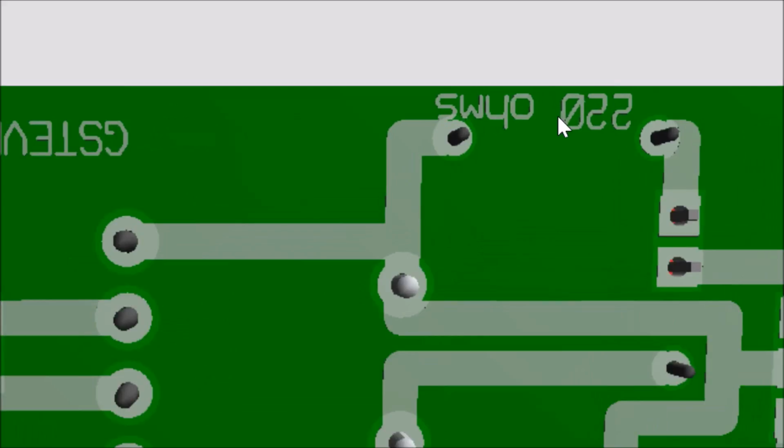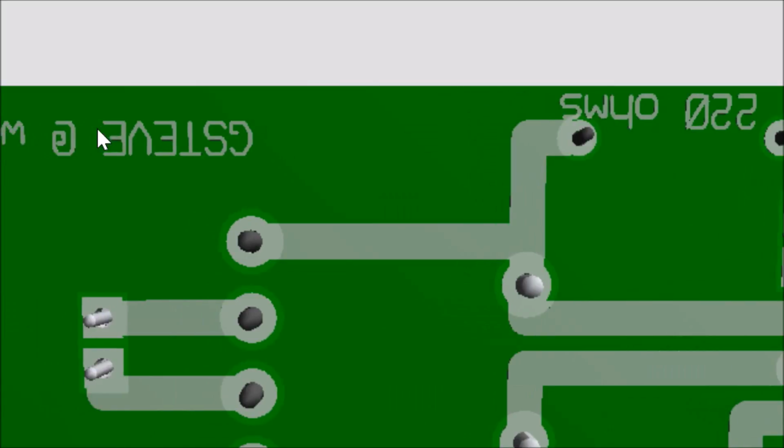I want to point out something. You can see that my LED is really touching this copper, but make sure that this and this are not ever touching together. So you can go ahead and shift this in your own design so that it doesn't touch this copper at all. Check it out and be able to separate it.